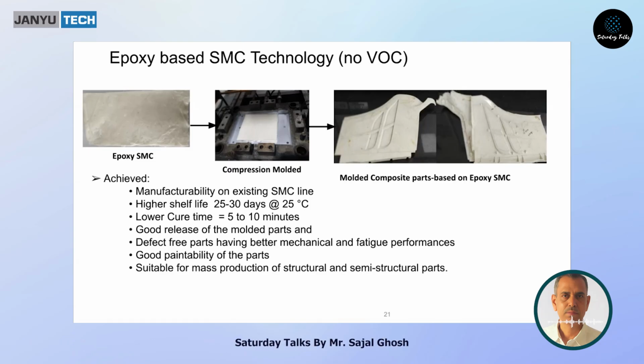at CD only, because after a certain point they cannot really help. So this material, epoxy, cycle time, what is the cycle time? It is very high. In unsaturated polyester based, vinyl ester based SMC, the cycle time for a product of, I can say, this 3 meter square area product of 20 kilo, your cycle time is maybe 7 minutes.